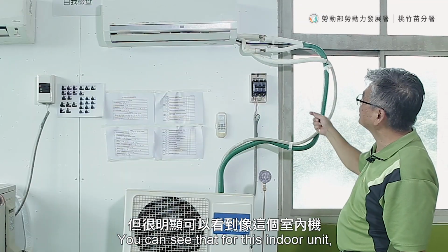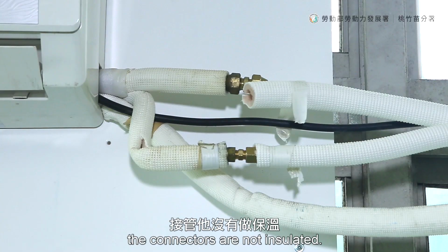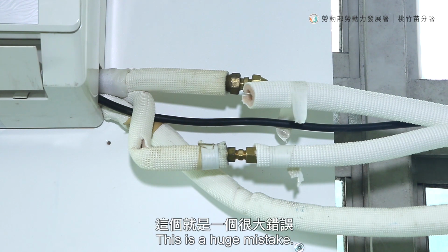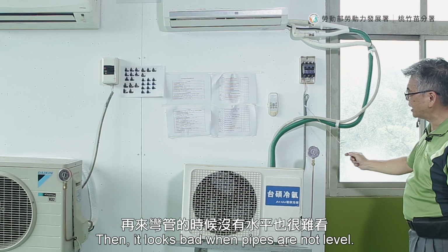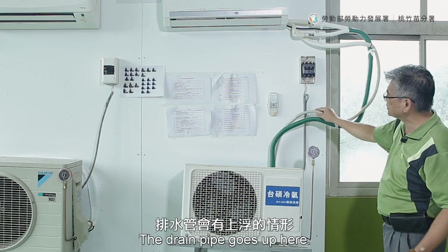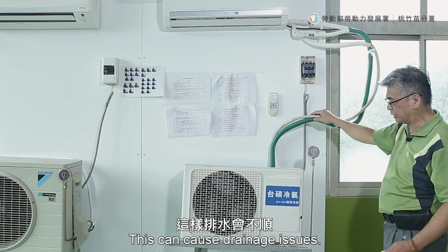You can see that for this indoor unit, the connectors are not insulated. This is a huge mistake. Water may leak from here. Then it looks bad when pipes are not level. The drain pipe goes up here. This can cause drainage issues.